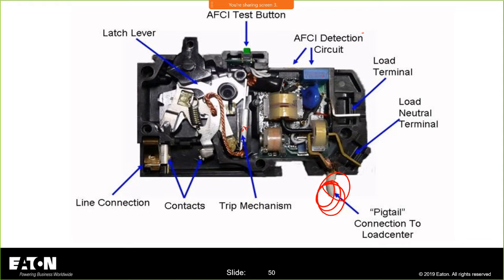Now, I know Eaton was an innovator back in the branch feeder days, and we came out with a plug-on neutral circuit breaker. It was popular. It wasn't as popular as it is today, because expansion of AFCIs leaves that panel board with a lot of AFCIs, so those pigtails get kind of busy in the trough. I'm not sure how many manufacturers offer a plug-on neutral, but I know we do from an Eaton perspective. The plug-on neutral gets rid of the pigtails, cleans up the trough and makes a nice clean installation. You can't make a mistake because you're plugging onto the neutral.